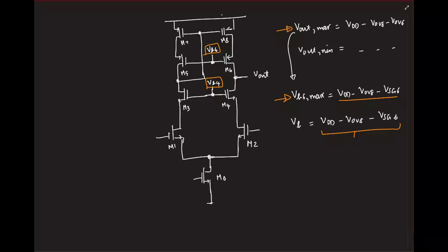Yeah, you suggested diode connection. Like two cascode transistors and they will be diode connected. So you're saying like this? And what should I connect here? What currents should I have here? I0 by 2, I0 by 2. Okay, so he's suggesting this. So let's see what we get here.